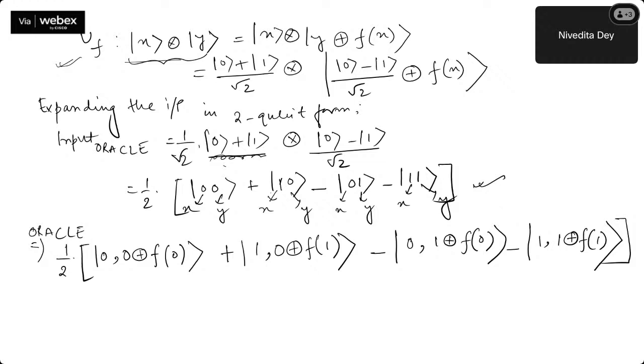Okay, thank you. Now, what will happen if I take anything, f0, f1, f2, say p. So p XOR 0. XOR of anything with 0 will only be that variable itself. So a XOR 0 is a, and a XOR 1 is basically a bar. That is a very simple thing.